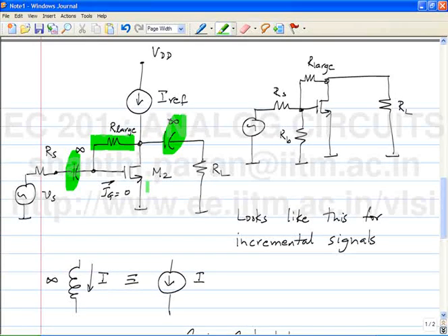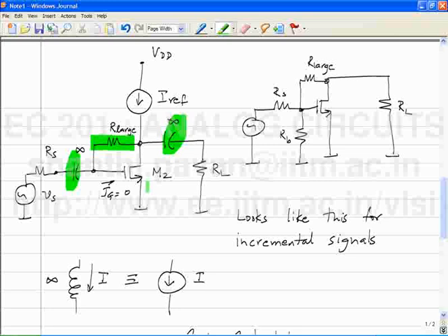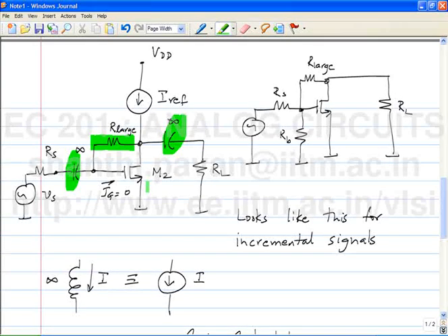So obviously, once you have chosen VGS, which means once you have fixed I or Iref, the VGS and by way of topology the VDS are both fixed. Okay, so this again drives home the point that there is no free lunch. We thought we got rid of one transistor, but this is imposing certain other constraints.